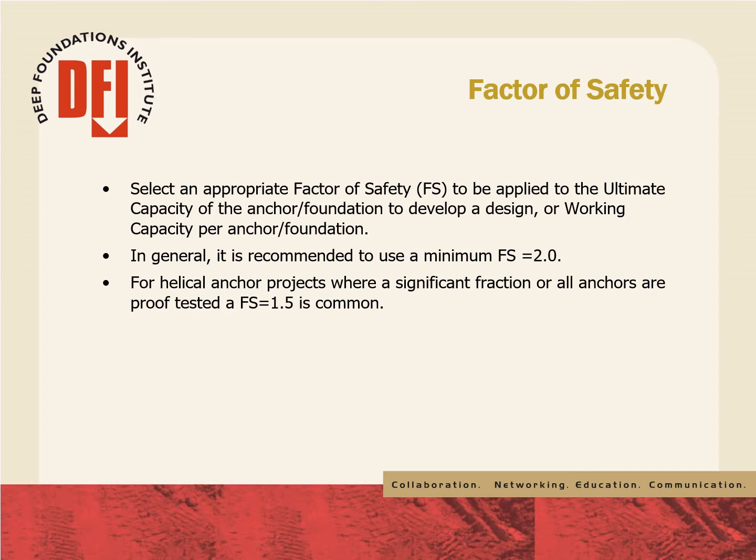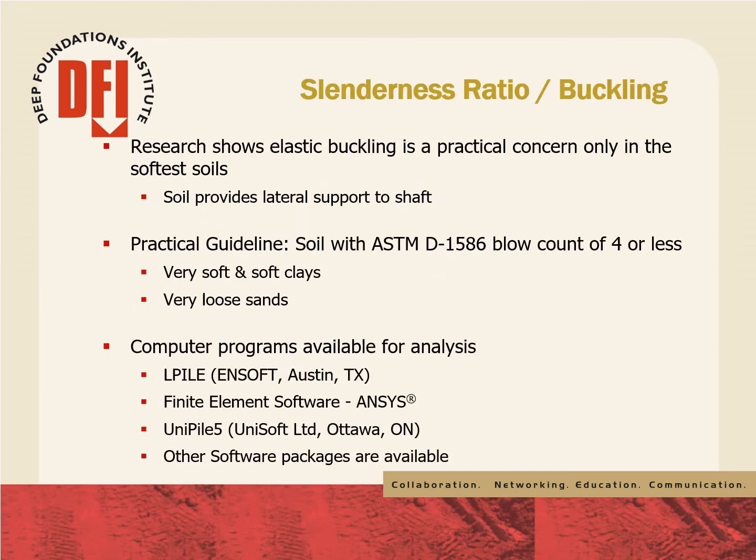The most common factor of safety used for most permanent helical pile applications is a factor of safety of 2. Applications where extensive testing is required allow for lower factors of safety. Research shows that buckling is a practical concern only in the softest soils.